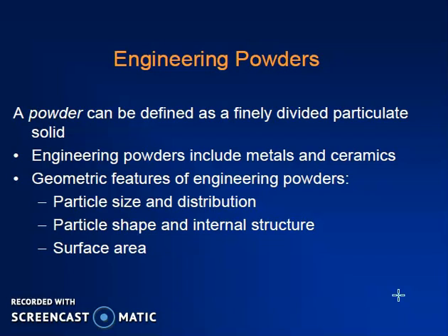A powder can be defined as finely divided particulates of solid. Engineering powders include metal and ceramic powders. Then the geometric features of engineering powders are particle size and distribution, particle shape and internal structure, and the surface area of the powder.